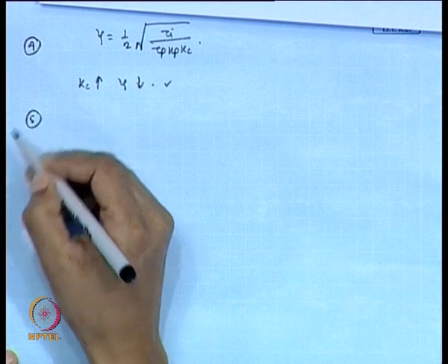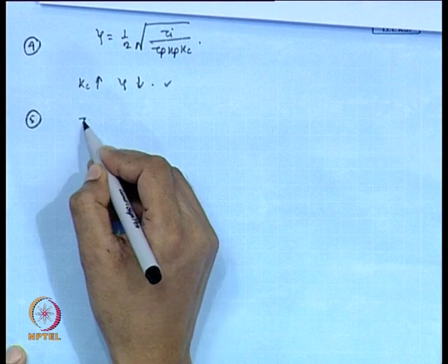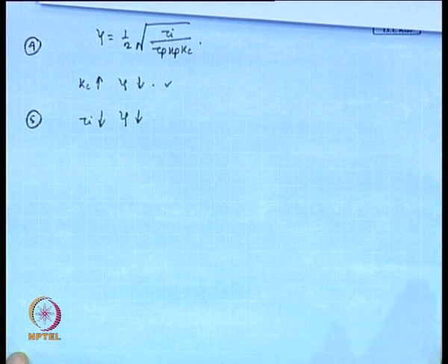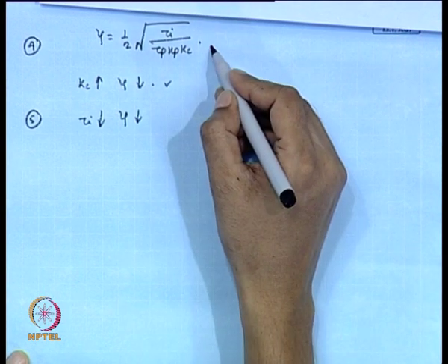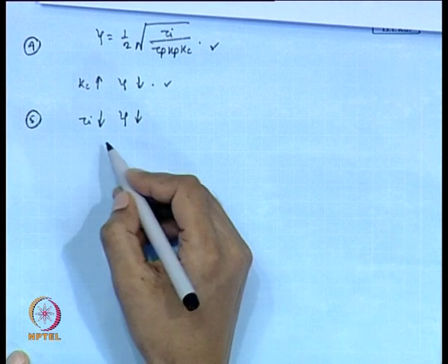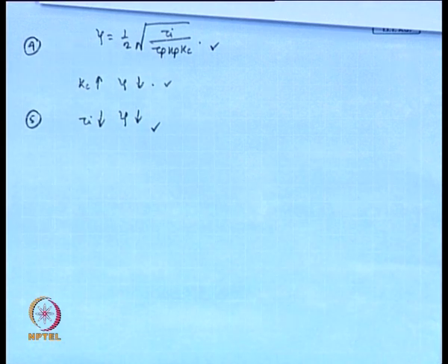In the same line, we can conclude again that with the decrease of tau I, zeta decreases. You see the expression of zeta, it is clear that with the decrease of tau I, zeta decreases. So, if tau I is sufficiently small, the overdamped response may move to underdamped response with large overshoot and decay ratio. Fine.